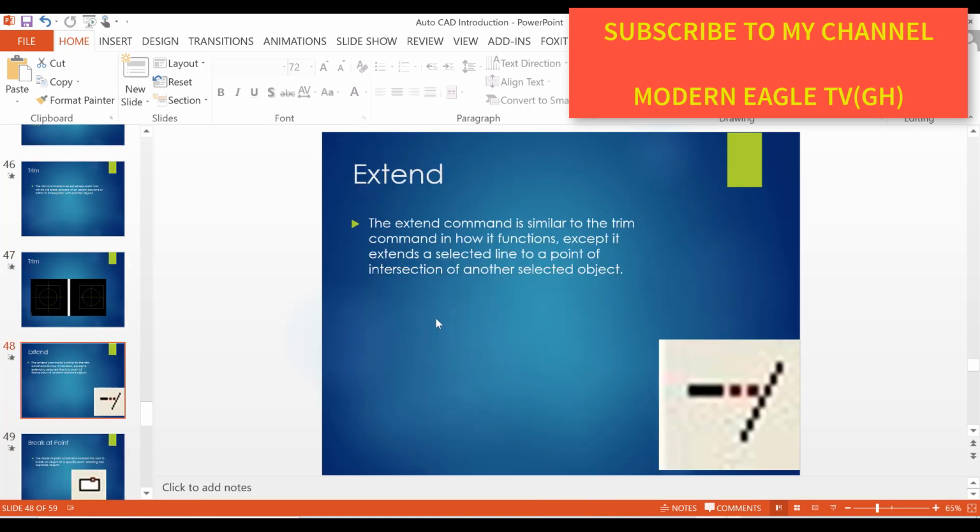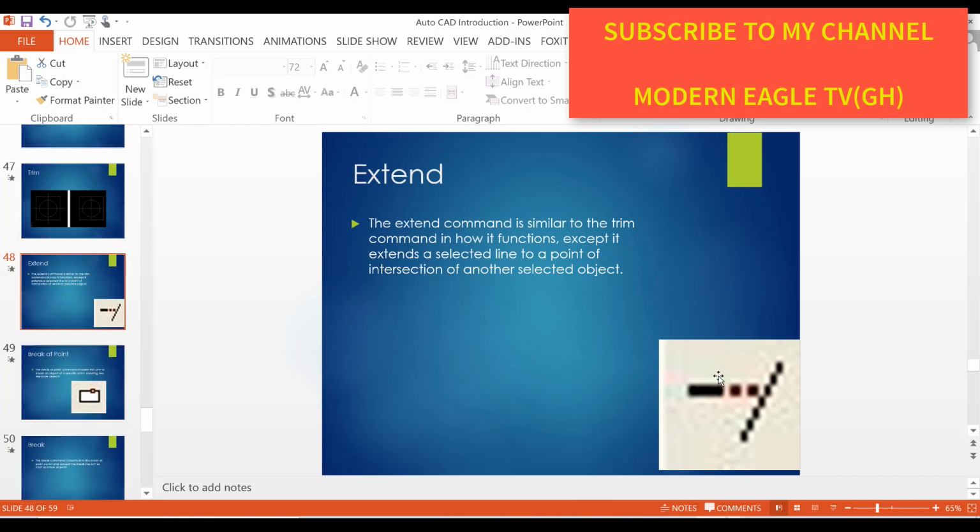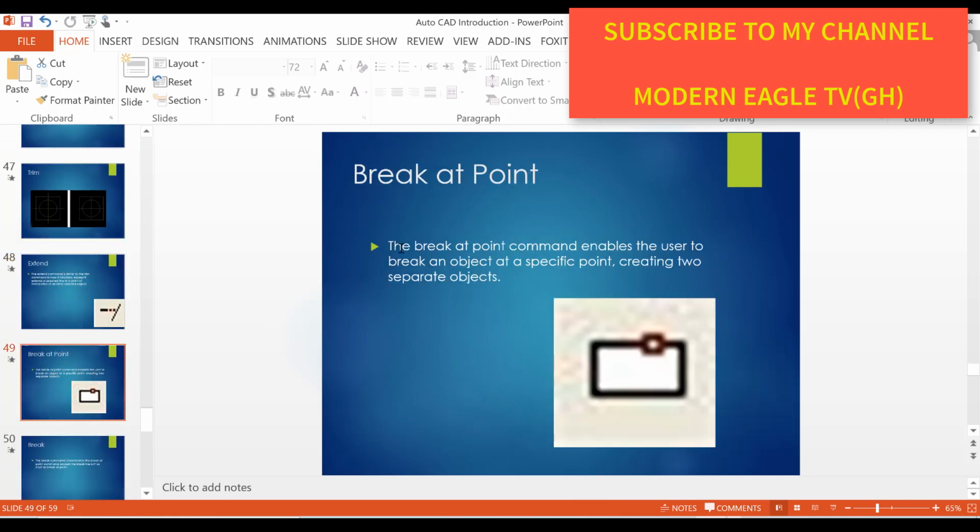Extend. The extend command is similar to the trim command in how it functions, except it extends a selected line to a point of intersection of another selected object. You can see the symbol. Break at point. The break at point command enables the user to break an object at a specific point, creating two separate objects.